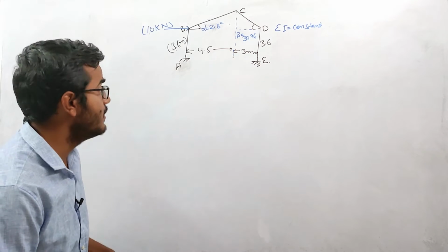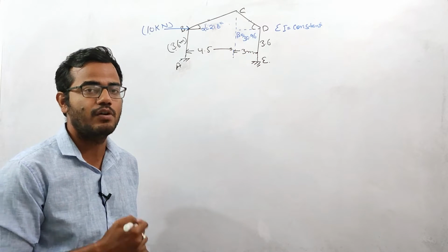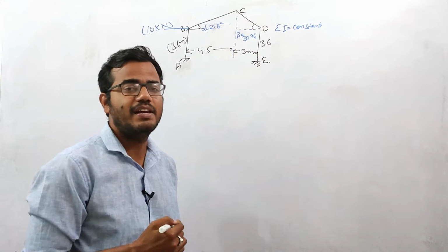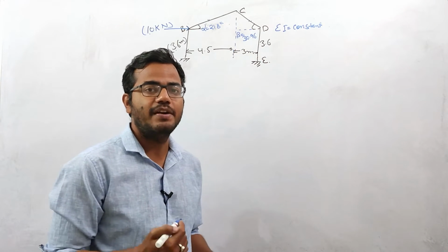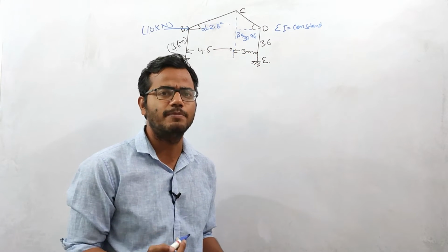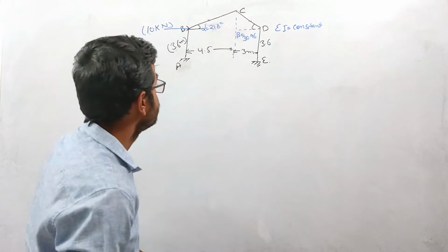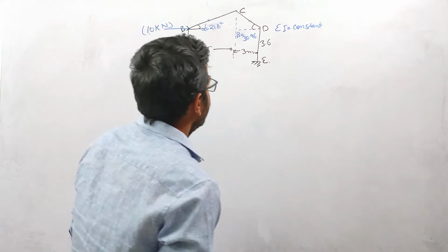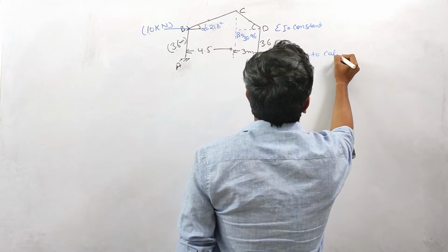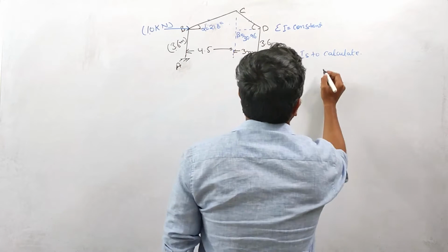In the slope deflection method, the initial thing which we need to find is the kinematic indeterminacy of this frame structure, right? Because the kinematic indeterminacy is basically the unknown displacement, and with the help of the unknown displacement, we will be calculating the internal forces generating in the members, right? So now let us first calculate. First step is to calculate the kinematic indeterminacy of this frame.